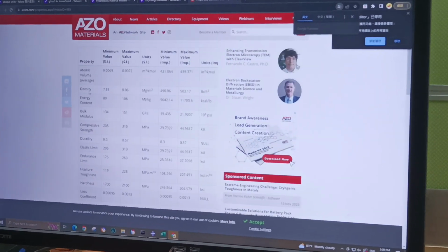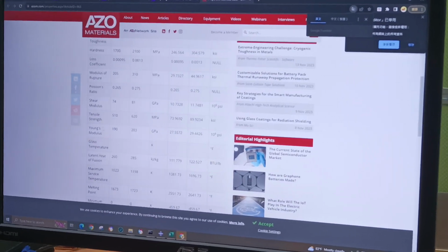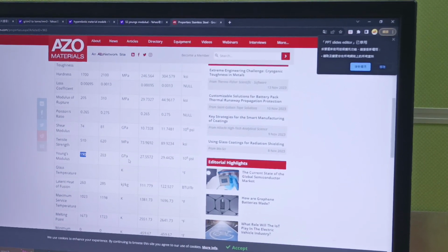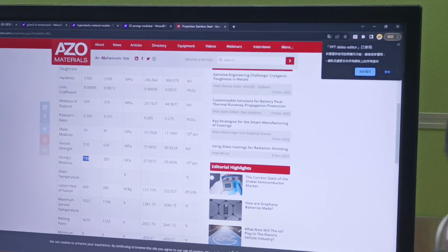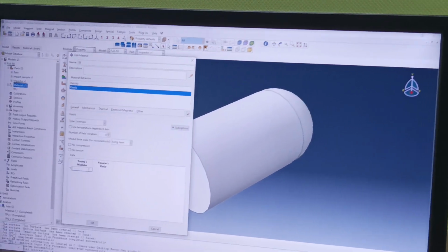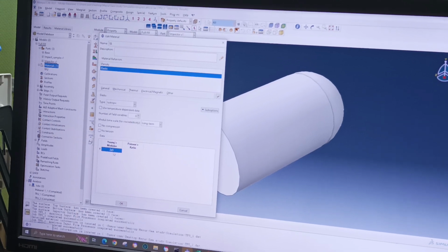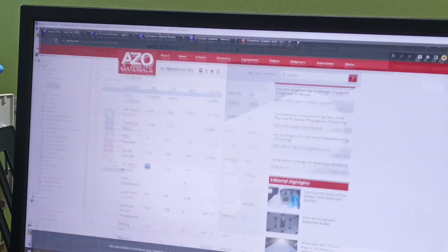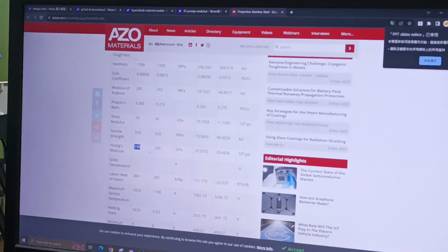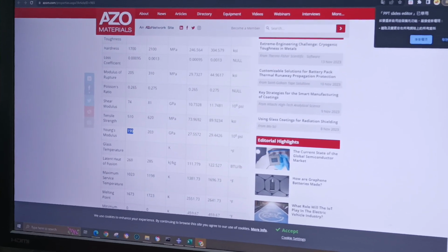You see the Young's modulus is around 190 GPa, but we have to make it MPa. So there will be 3 more zeros, because the unit needs to be megapascal. So I just select 2e to the power 5, because it will become around 200,000. Gigapascal, right? 200,000. Yeah, e to the power 5, correct.